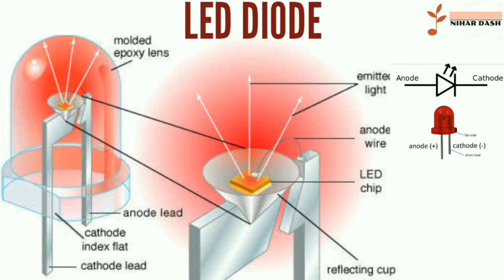The luminous efficacies of typical AlInGaP LEDs and InGaN LEDs for different peak wavelengths are shown in the table below. The efficacy depends on the light energy generated at the junction and losses due to reabsorption when light tries to escape through the crystal. The high index of refraction of most semiconductors causes the light to reflect back from the surface into the crystal and be highly attenuated before finally exiting. The efficacy expressed in terms of this ultimate measurable visible energy is called the external efficacy.